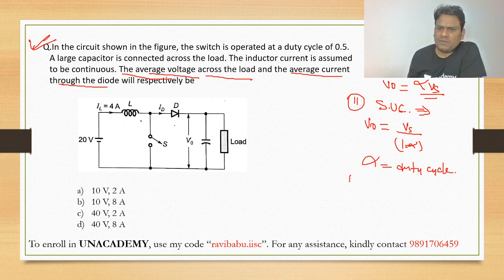And the last one, which is similar to an auto transformer in the AC case, is the buck boost converter, and a buck boost converter can provide both types of result, similar to step up chopper and step down chopper.